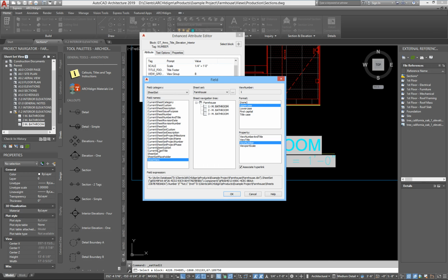As it's been placed over on a sheet, it connects to a sheet view, and that's why you see the views over on that sheet. So here's the sheet, and it's showing you each of those views as they've been brought over, and so you can actually repath something. If this thing had been inadvertently blown out, you could manually come in and just reset it to the one that you want it to go to.